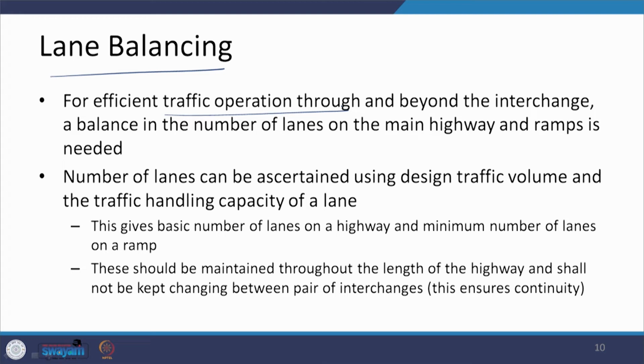Now, when we are looking at this, what number of lanes needs to be provided? One thing we have already discussed when we talked about the ramps is that it is dependent on the total amount of traffic, and with respect to that we also look at the handling capacity of a lane, and that will define whether we need to have 2 lanes or 3 lanes or more than that.